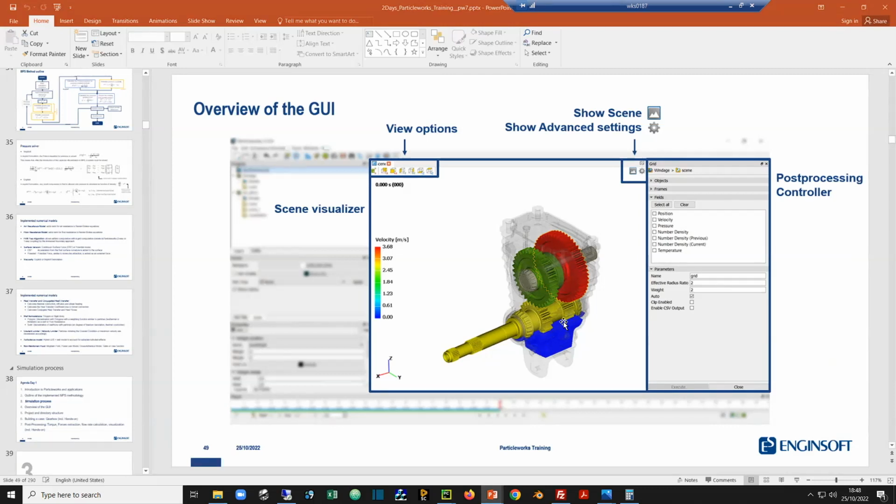You much sooner get a computational limit than other more sophisticated considerations in terms of how small you can get, because as you halve the particle size, you will look at approximately 10 times slower particle simulation because of the scaling of the number of particles you generate. If you think about the scaling of the volumes, as soon as you halve the particle dimension, you can expect that the number of particles you generate grows quite significantly. It's not a factor of 2, but a factor of 8, 2 to the third power.